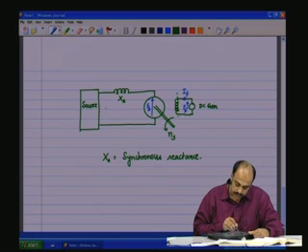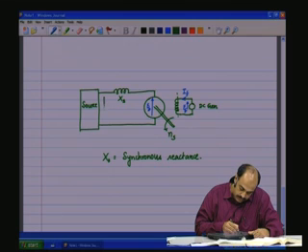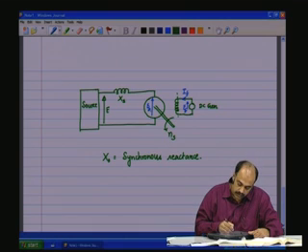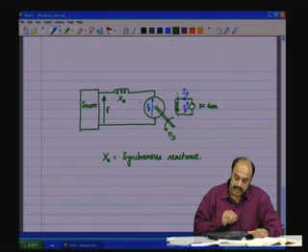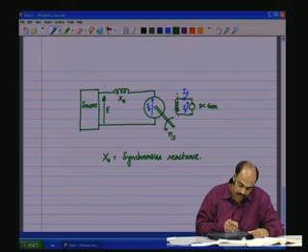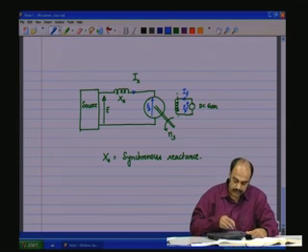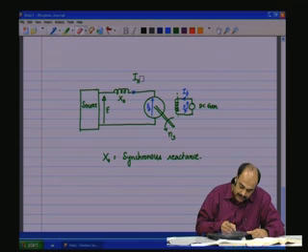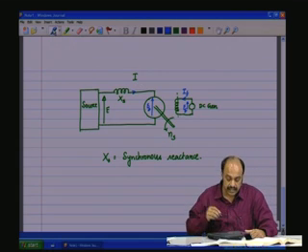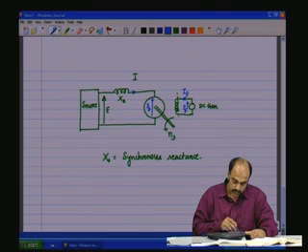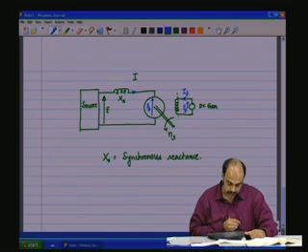Now, the source voltage, we shall call it E. The voltage which is generated as a back EMF is EB, and there is a current, which we will call IX. This is the current IX which is flowing through the synchronous machine, or we'll just call it the current I. It doesn't make much difference, because that is the only current which is flowing into the stator. So E into I will be the apparent power, of course.